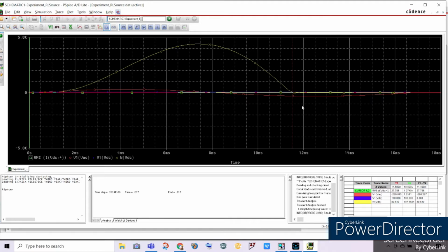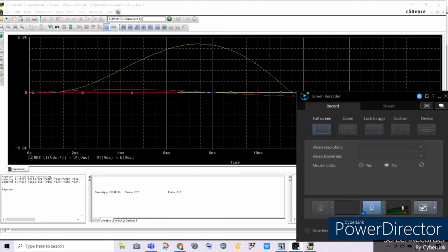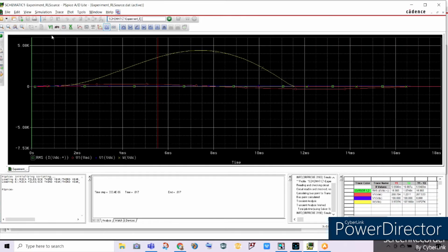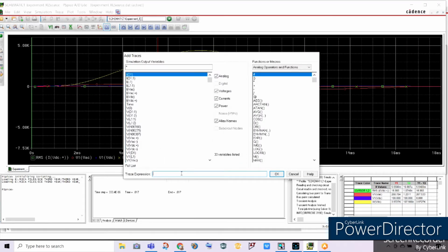This has the same concept wherein our average power started to rise, meaning there is a noted flow of current to our circuit down to our voltage DC source, and then it falls down again to 0 when there is no current flowing in our components. To have a better understanding, let's add another trace, which is the average power across our inductor connected to our voltage DC source. Let's put a parenthesis on our expression for it to run, and then run it.